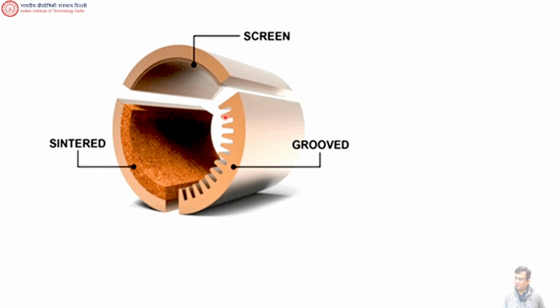Ultimately, this sort of structure will give you this kind of meniscus. One kind of meniscus at the evaporator side, another kind of meniscus on the condenser side, and then these things are going to do something which will drive the liquid through the wick, even if gravity is opposing it, right?